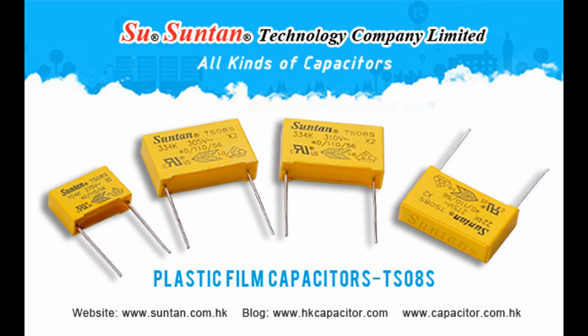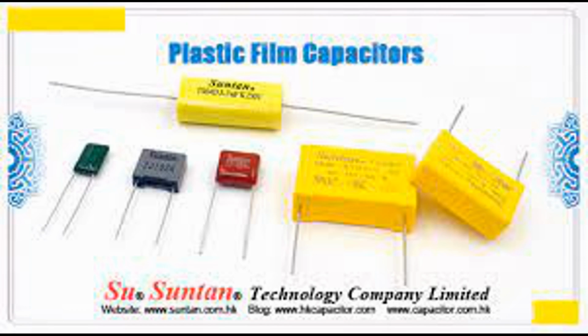3. Long lifespan. Durability. Film capacitors have a long operational lifespan compared to other capacitor types, particularly electrolytic capacitors, which are prone to aging and wear over time. Self-healing properties. In metalized film capacitors, if a dielectric breakdown occurs due to high voltage, the capacitor can self-heal. The thin metal layer vaporizes around the fault, isolating the damaged area and restoring functionality without affecting the rest of the capacitor. This extends their lifespan and reliability.